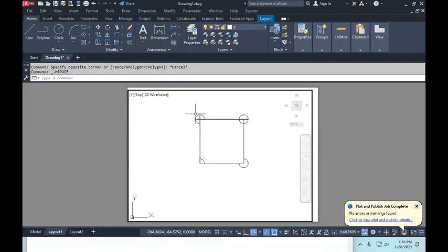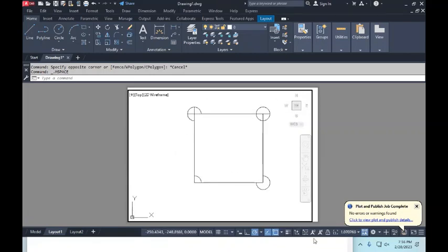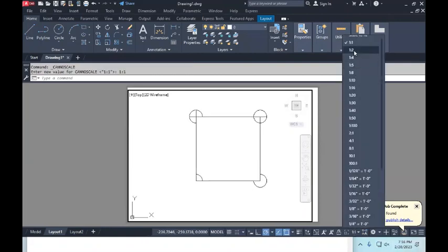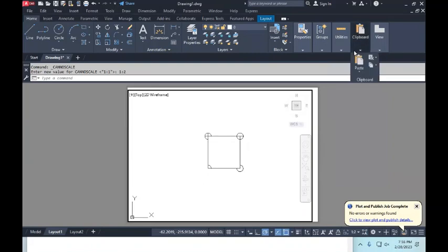Okay, but if you are inside the viewport and if you zoom in and out, you see the scale is here. Pay attention to that bottom corner where the numbers are. Right. I'm inside my drawing space and I'm zooming in and out. You see the scale changes? Got it? Right. So if I need a scale of 1:1, there you go. That's 1:1. If I need a scale of 1:2, that's 1:2. So that is how you will set scale for your exercise. I think the scale you are asked to use is 20:1, isn't it? Because 1:20. No, it's 20:1. Yeah. So how do you catch this is if you look at the dimensions in a drawing, they are pretty small. And once you draw out your exercise, you will think the drawing looks small. But when you scale it up, because you are using an enlargement scale, okay, a scale is 20:1, right?